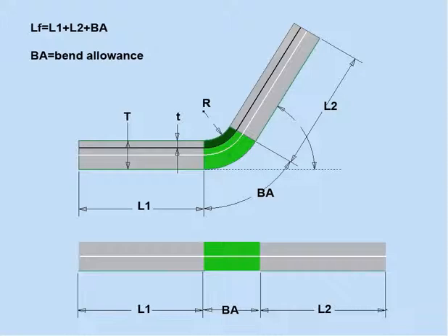That's why bend allowance varies for each combination of material type, thickness, bend radius, bend angle, and different machining processes, machining types, machining speeds, etc. The list of variables is indeed extensive. And of course, for that reason, calculating the bend allowance by trial and error remains a pretty popular method. The value of bend allowance that is derived from textbooks or from manufacturers and suppliers is usually provided in table format and looks like what I'm pulling in right now.